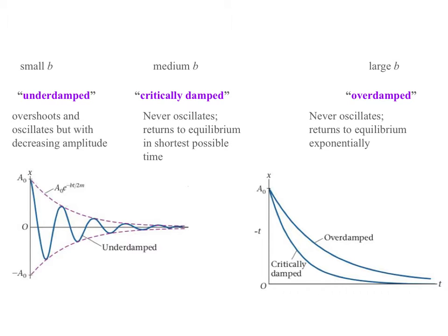When B is a small number, the system is underdamped. It's being dragged, but it's able to move. So it goes through its equilibrium and oscillates the way an oscillator should. But as it comes back, it gets less and less speed. As energy comes out, it will have less and less amplitude because of the half kA squared, right? If the energy is going down, then a half kA squared is going down, so A squared must be going down.